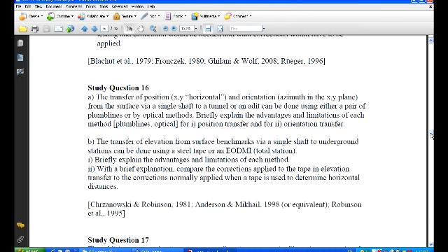One of the problems with using an optical plummet is visibility. Obviously you have to be able to see whatever's at the other end in order to line it up with the image of the crosshairs. So usually the limitation on using an optical plummet is visibility.